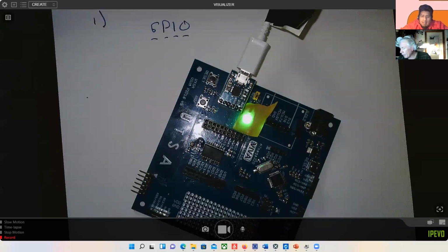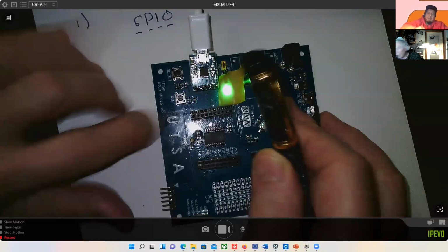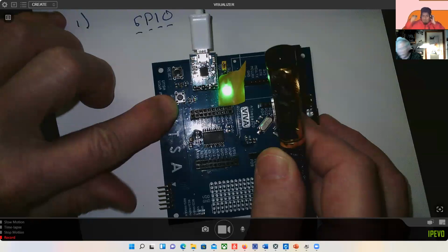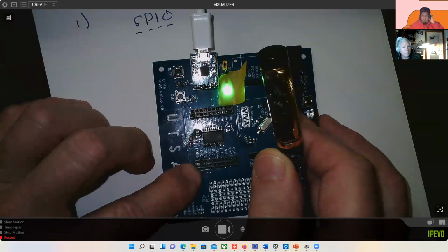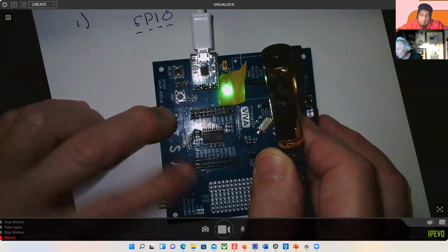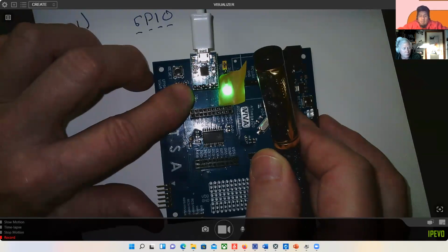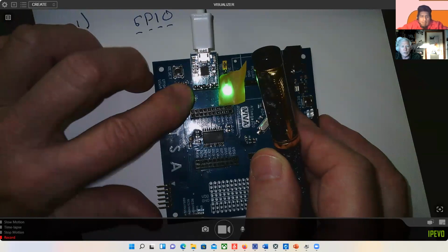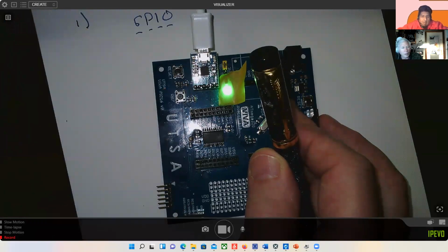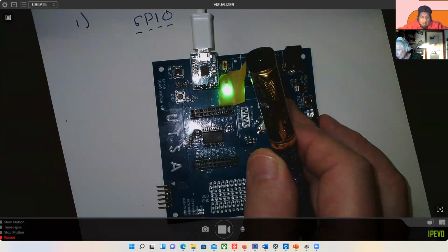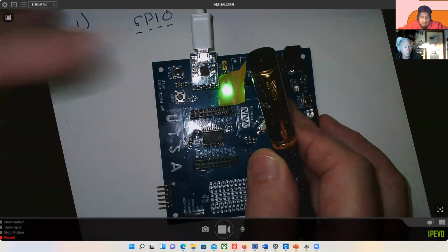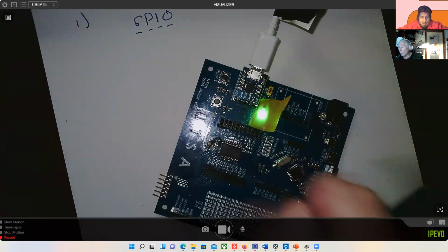Okay, so anyway, this is the RB7 push button. It's connected to port B pin 7, and when you push it, it'll ground that pin, so it'll input a 0 if it's set up as an input. When you release it, it's pulled up to whatever the operating voltage is, so it'll read a 1. So pushed is a 0, released is a 1.